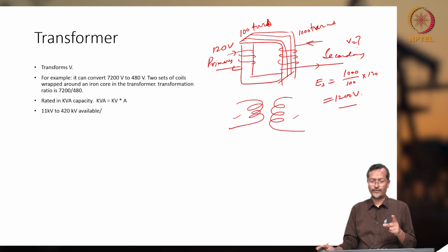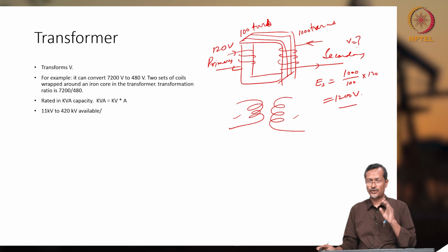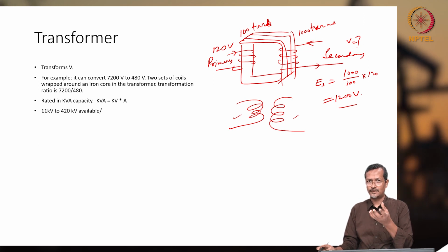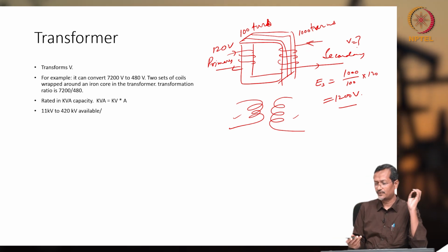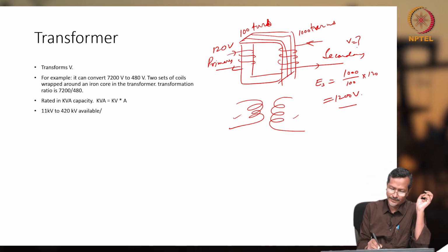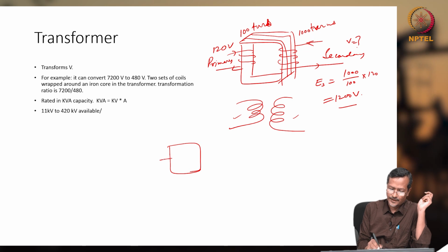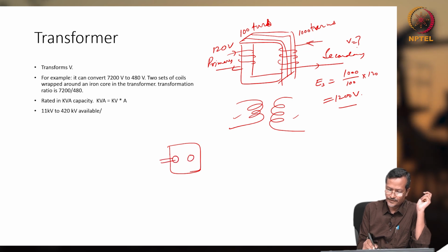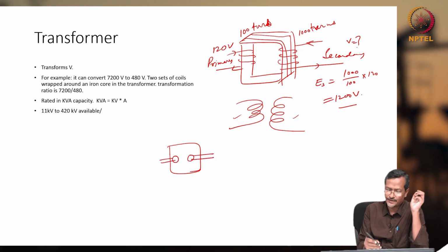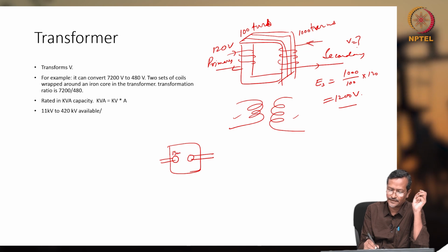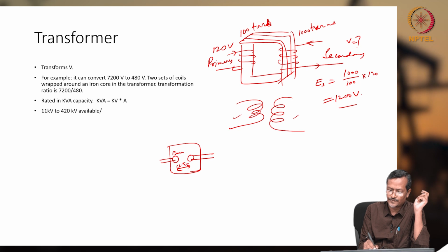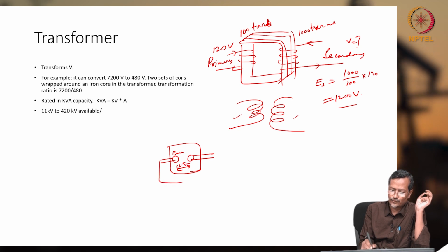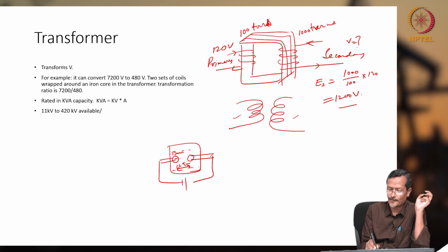Okay. When we are talking about a transformer, we are talking about transformer oil or motor oil, or the dielectric fluid. So, how do they test the dielectric fluid? Normally, they will have one vessel, okay, and there will be two small beads. This will be 13 millimeter each, and there will be a certain gap, let us say 2.5 millimeter, and you apply potential, and you put this in the dielectric fluid.